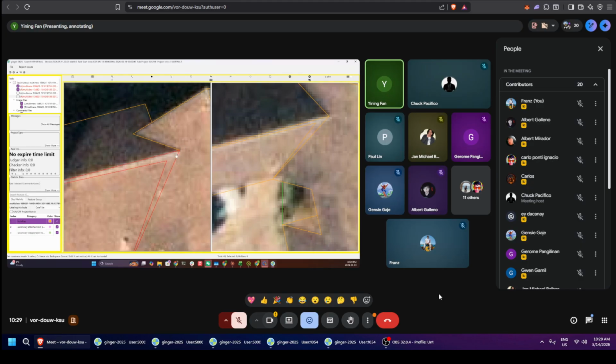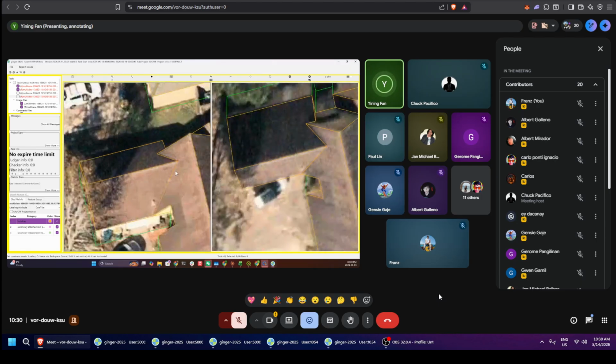For end mode, you first go to A and hover over the points you want to fix. For example, you want to fix it at a location and you don't want to move it. For example, you want this thing to be attached to here. Then you press O. This point will be fixed at this location, at this space. It won't get moved. And then you hover to the point you want to attach, press Y, and there's the blue dot highlighted. Then go back to this point, press Y again. It will snap back to it. The same procedure can be done for point to line, line to line as well. That scenario can be tried once you have the actual task.